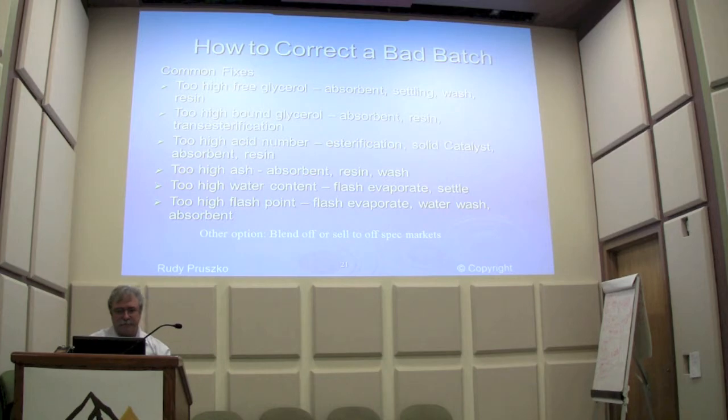So what's your water guideline going into a base reaction? What do you want it to be less than? 500 parts per million total. 0.05%, right? Mm-hmm. There was a discussion earlier that there's kind of a trade-off between your initial titration for FFA and the acceptable PPM for water, where if you titrate lower initially, then it's possibly acceptable to have more water in your oil. Do you have any feelings about a balance between the two there?